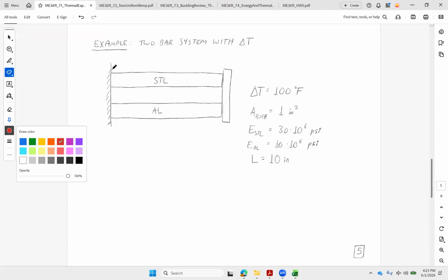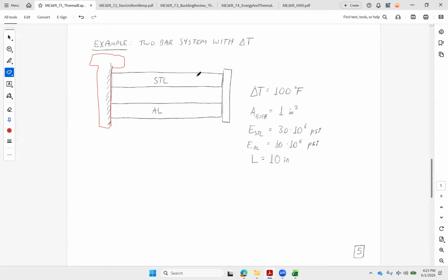So we've got some bolt or attachment that's affixed through one end of it, and then some kind of fastener attached through the other end. And it guarantees that they're going to either expand the same amount or contract the same. Now, the loads that are inside each one can be different, but the total displacement and therefore the total strength are going to have to be the same.